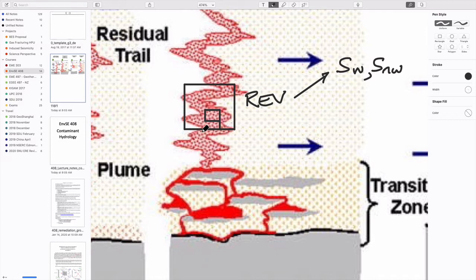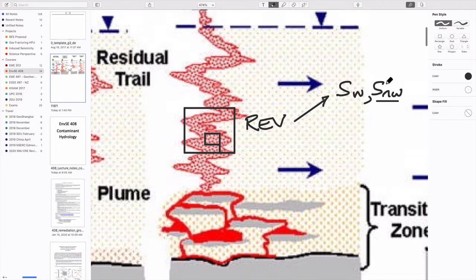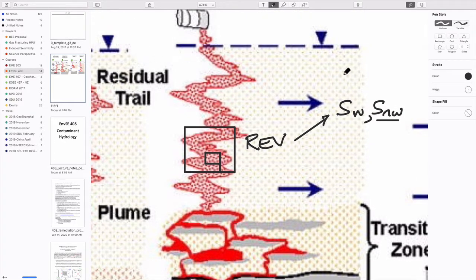And our reason to do that is that we'd like to be able to figure out from the non-wetting saturations exactly how much mass is there. And if we know how much mass is there, we have some idea of the mechanisms that we might use to get it out. We know that if the saturation is relatively low, and we've worked on these two figures, which I'll draw again. You've seen these ad nauseam, I think, but let's do them again and do them on top of each other. You know it's going to be a relative permeability and a capillary pressure versus saturation curve